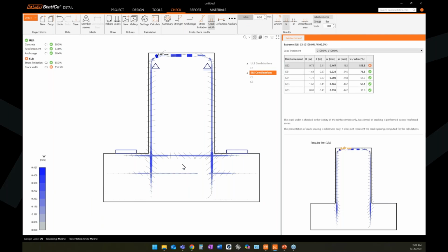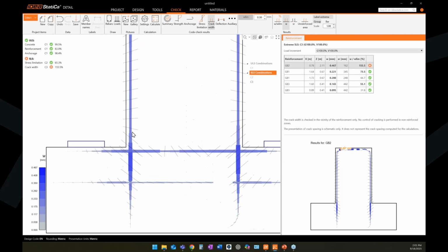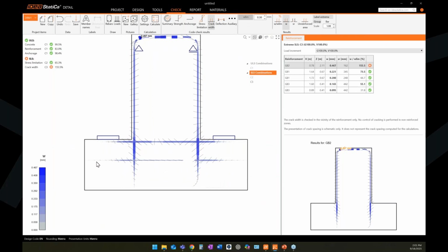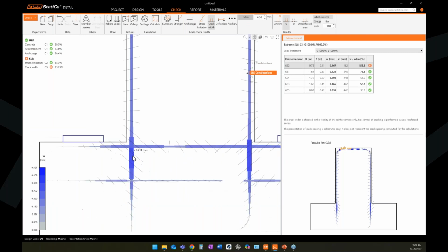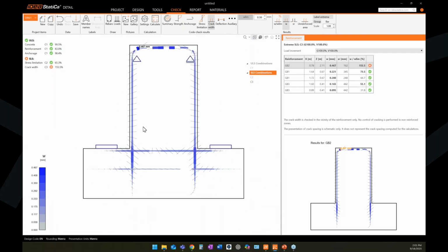Of course at the junction for sure. Because we're mostly interested in the bottom part of the beam. We can actually neglect the top part. This is not our scope for this type of the beam. We're interested in seeing the behavior at the junction, at the bottom part of the inverted T beam. So we see the cracks, we see unsatisfying results.